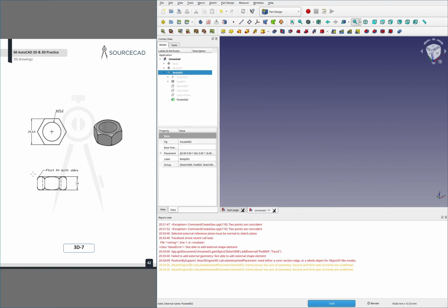And I guess specifically, I'm talking about this fillet, because you notice that you can't actually make this fillet with the fillet tool because it's not tangent. Oops, that's not a very good arrow. Because it's not tangent at these edges right here. It's only actually tangent kind of in these corner bits here. So kind of an interesting shape.